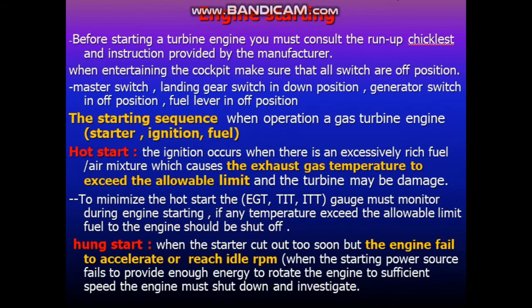Now, what's the meaning of hot start and hang start and their relation with the engine? The hot start: the ignition occurs when there is an excessively rich fuel-air mixture, which causes the exhaust gas temperature to exceed the allowable limit, and the turbine may be damaged.